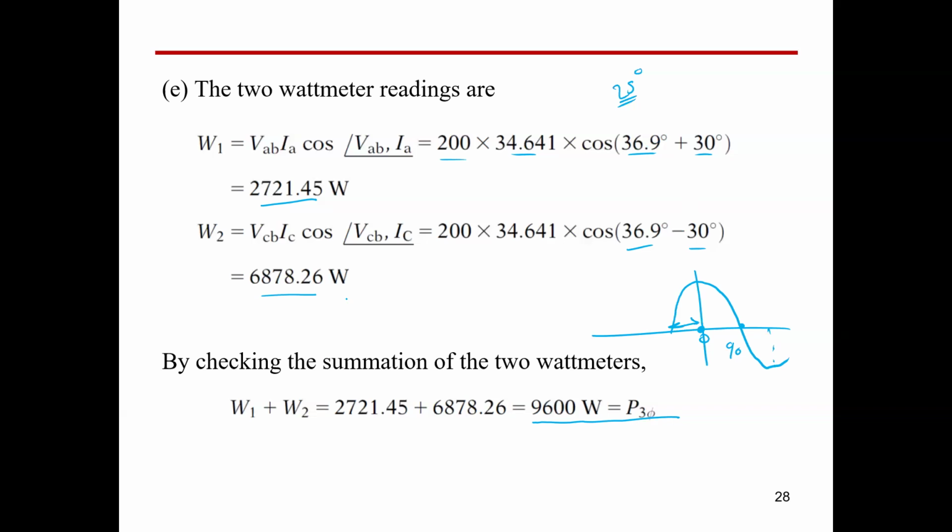Do we have something called negative power? Actually, we don't. But this is right if we connect this wattmeter to a single phase. This wattmeter device now is not connected to a single phase anymore. It's connected between two phases. So if you have the value of the wattmeter in negative sign, please don't neglect the negative sign. Consider the negative sign, which means if the first value is 1000 and the second value is minus 100, then total power equals 1000 minus 100 equals 900 watts.